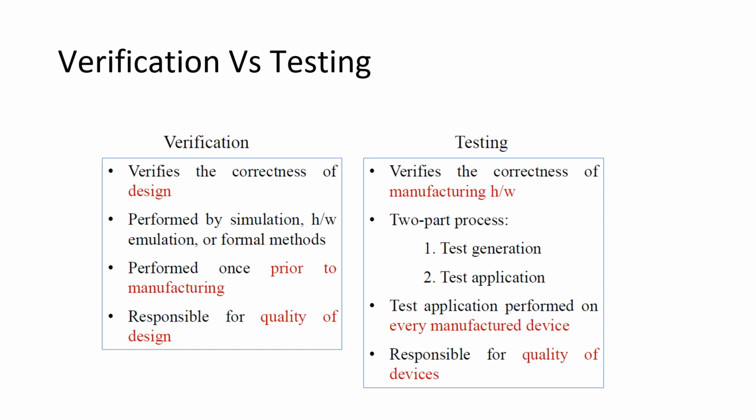Verification is performed before the tape out, or prior to manufacturing, and test is performed on every manufactured device. Tape out is only once, so verification is done only once, and it takes 70% of the tape out time. From start to tape out, if it takes 100% of the time, say 100 months, then 70 months goes just in verification. It's a thumb rule; it may change from chip to chip and application.